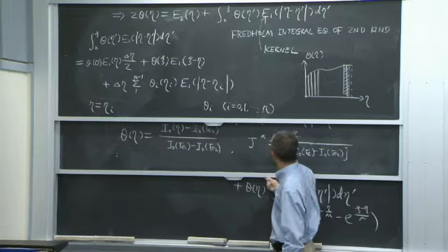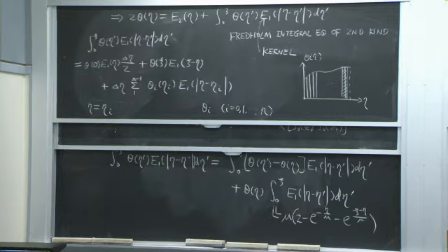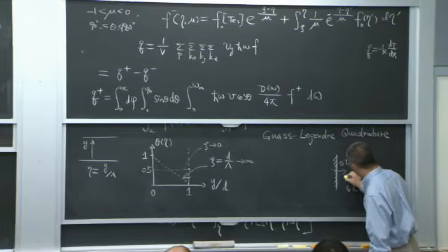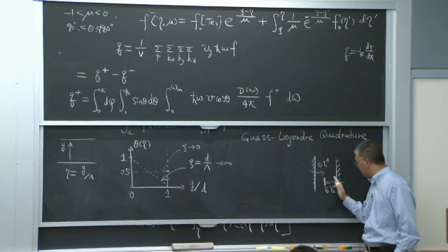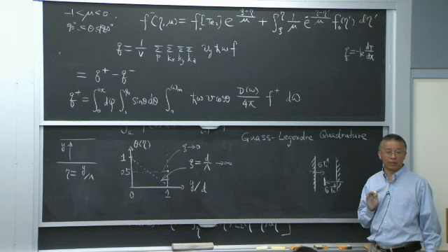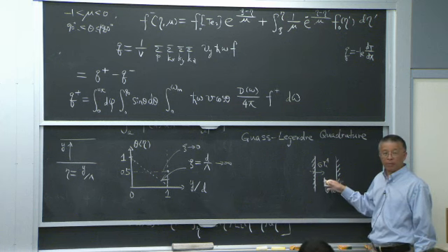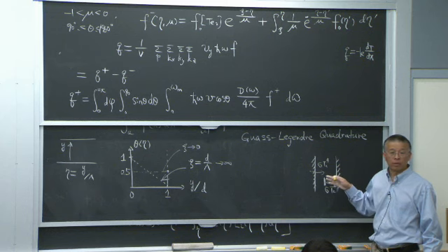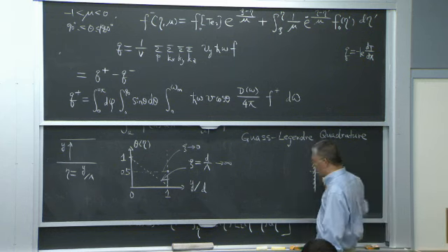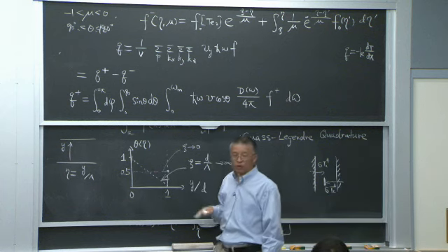This temperature is the equivalent temperature when I have this imaginary absorber that absorbs sigma T2 to the fourth power on this side, and on the other side absorbs sigma T1 to the fourth power. So equivalently, the absorber temperature will be the average of these two fourth powers divided by 2, right? And it's everywhere the same. So that's why in this limit, my solution is flat.